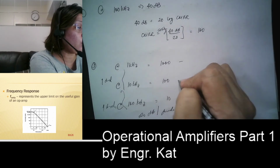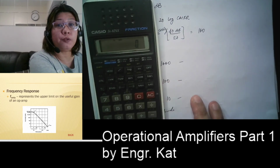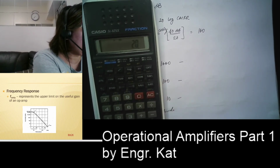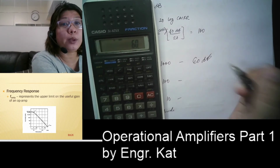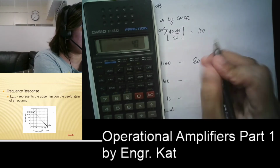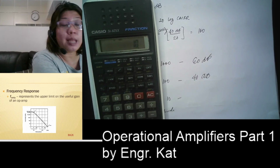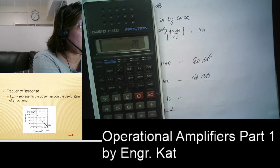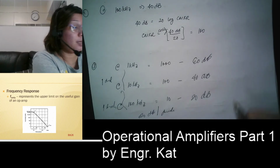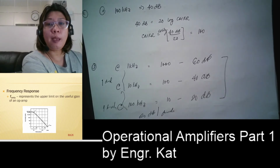If we convert this into decibels, 1000, logarithm times 20, is equivalent to 60 dB. Then 100, logarithm times 20, is equivalent to 40 dB. And then we have 10, logarithm times 20, which is equivalent to 20 dB. So you can see that this is decreasing at a rate of 20 decibels per decade.